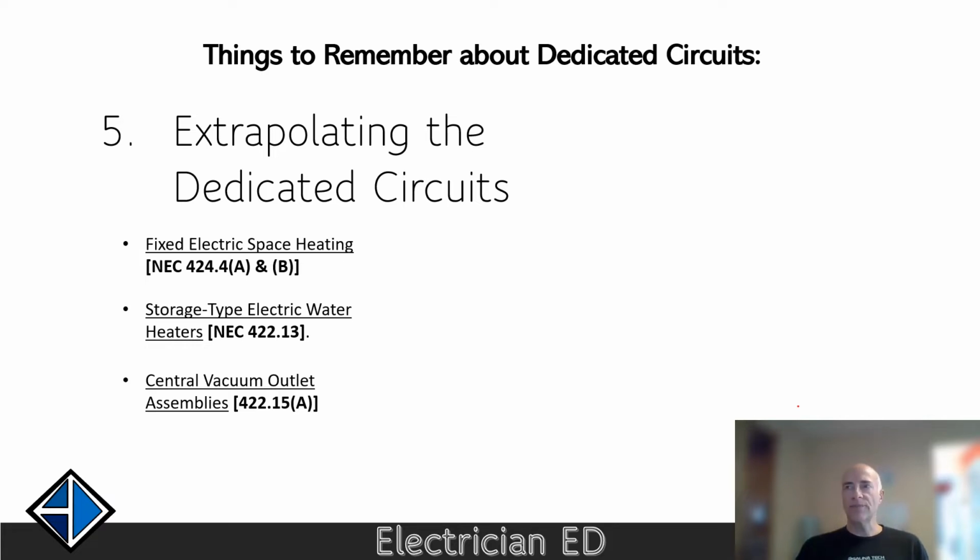Another thing that causes people just to throw up their hands and say, okay, manufacturers tend to recommend putting their systems on dedicated circuits. But that's not the same thing as demanding them. So you could figure out that, yes, you could put it on a general purpose branch circuit and you're probably going to be okay. Vacuums are only going to be used once in a while, and chances are you won't be using other things on those branch circuits. So the NEC does allow for that kind of common sense stuff.